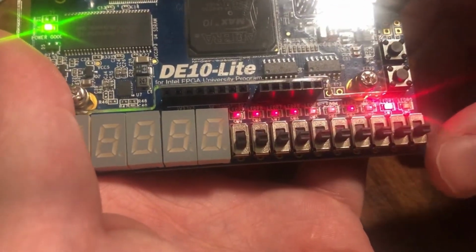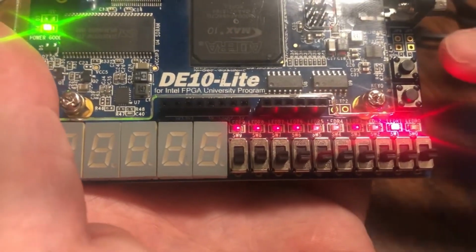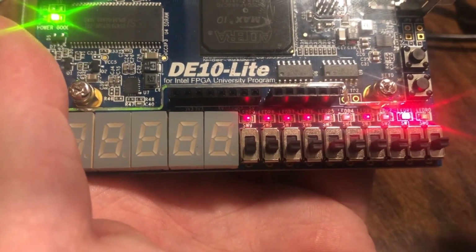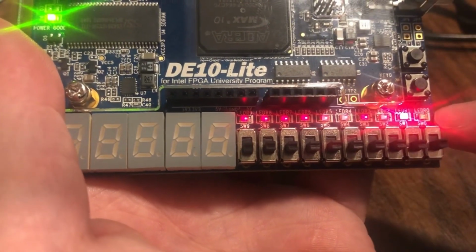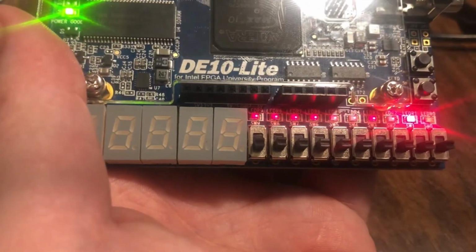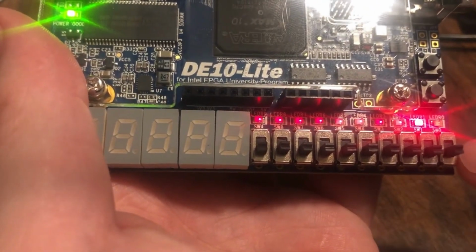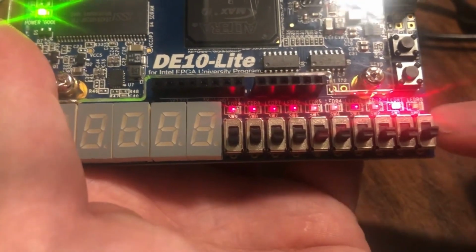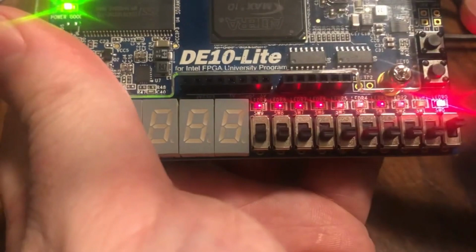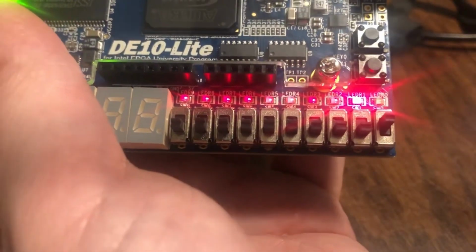And we have the input D here on this far right switch, and our clock is this button here. And aside from that, we should see Q and Q bar here, respectively, on LED R0 on this end here. So, as we recall from our truth table, if D is 0, then we should see Q bar go high when we clock it, and we do. And if D goes high and we clock that, we'll see Q go high, and we see that as well.